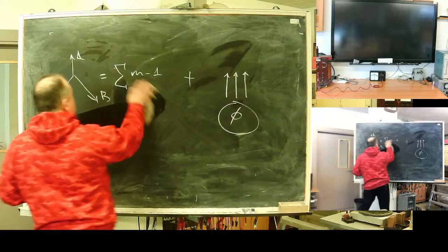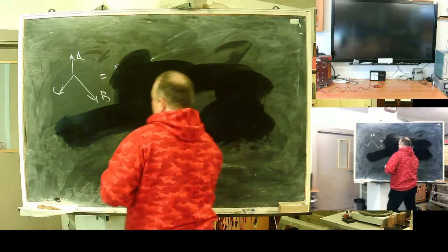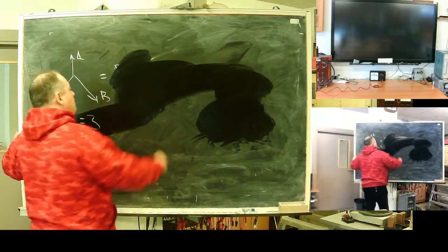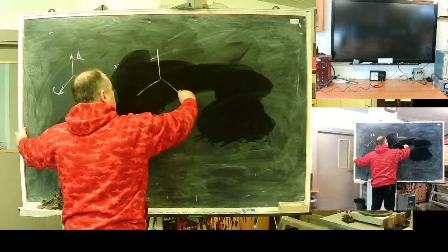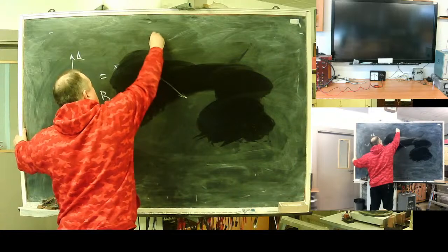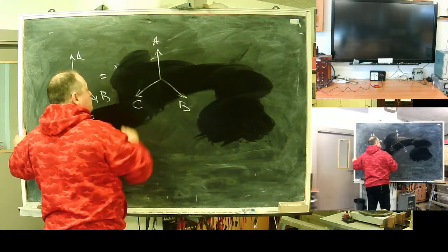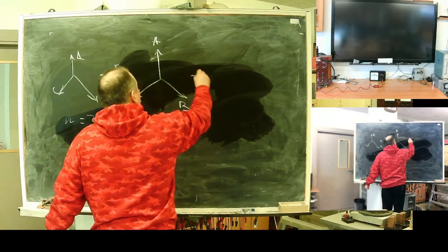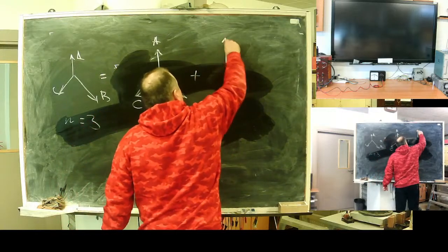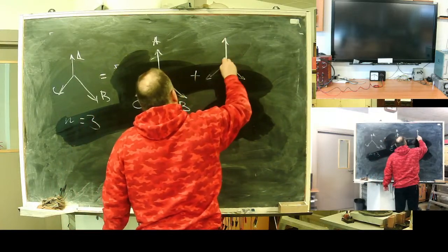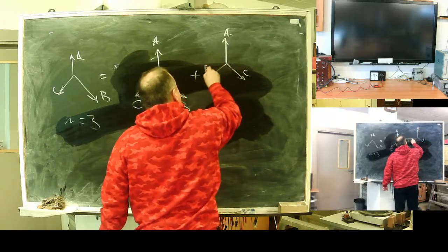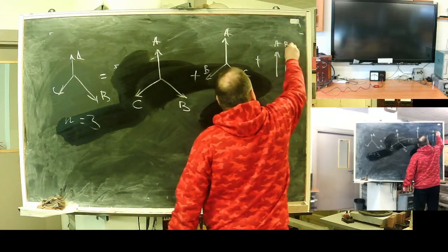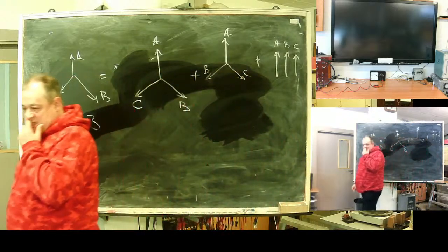In our case, where m is three, we have a three-phase system, and the Fortescue idea substitutes a real system with a set of three systems: two symmetrical, one with sequence ABC and one with the opposite phase sequence, plus an additional zero sequence system.